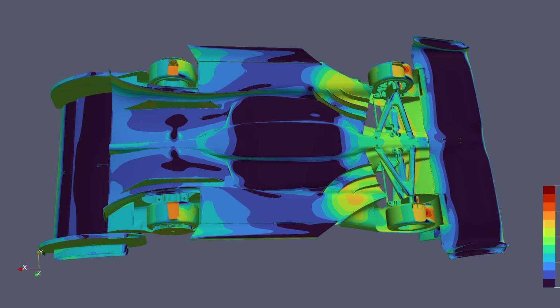Then once I had the rough design, I tried to balance the downforce between the front and rear. The balance in the downforce on the front and the rear has to roughly match the weight distribution of the car. I do have a little additional downforce in the rear just for stability because I find it's easier in high-speed turns to have understeer rather than oversteer.